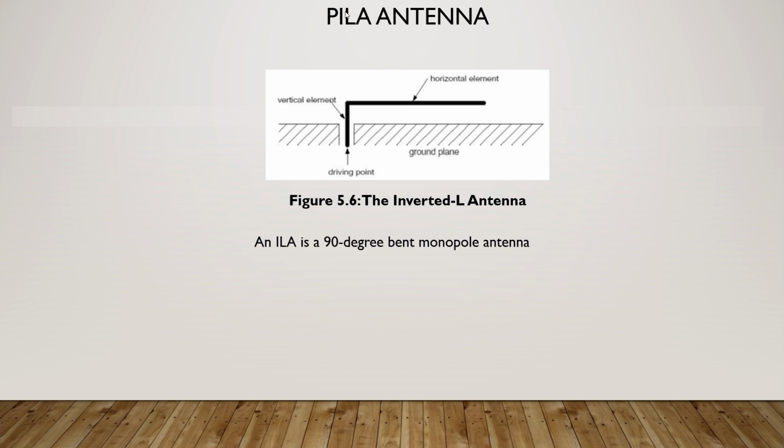Moreover, a quarter wavelength at our lowest frequency, 617 MHz, is 121 mm. In order to make a planar inverted L antenna radiate at multiple bands at the shortest resonance length, we need a novel antenna. We have learned that a current carrying wire radiates when it's curved, bent, discontinuous, terminated or truncated. We will put this theory to the test by creating a novel miniaturized antenna that radiates at multiple band frequencies.